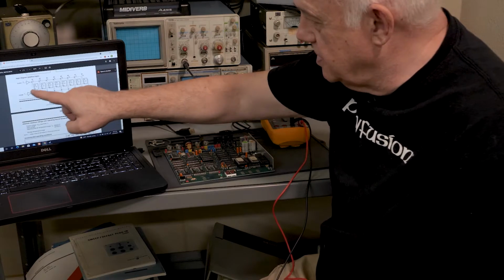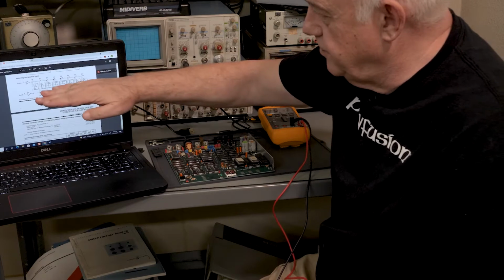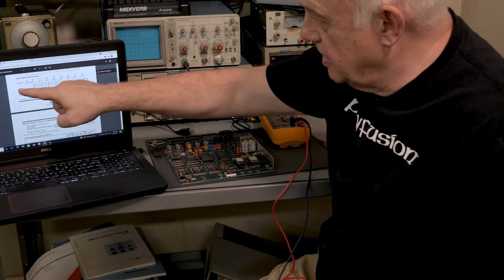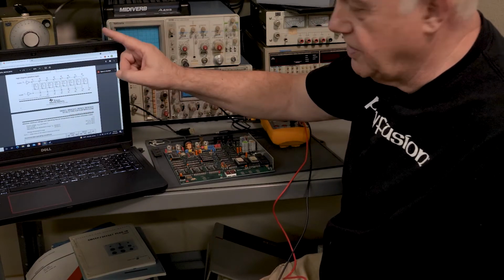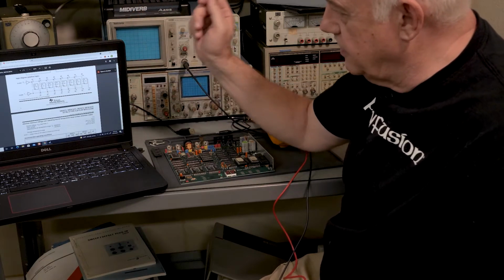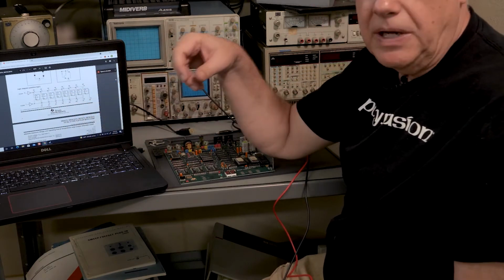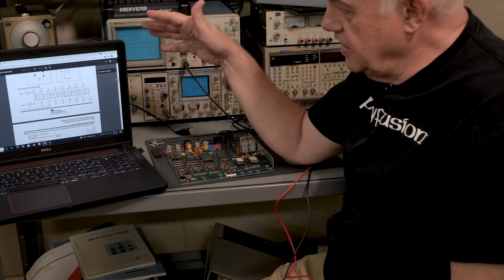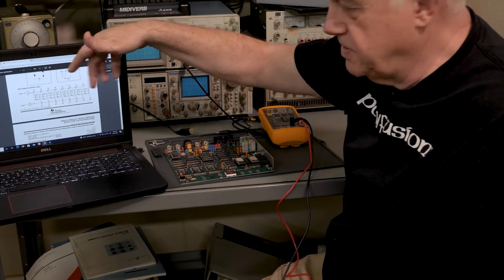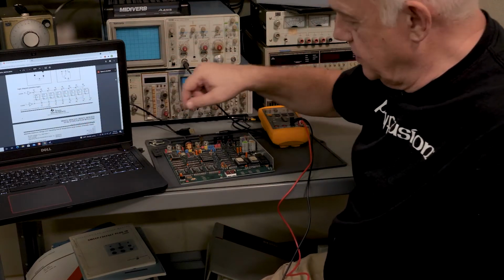You can see it has 8 individual flip-flops, 8 bits of data going in, 8 bits of data going out, a common clear that sets all the flip-flops to 0, and a common clock. This one happens to be rising edge. You can have rising and falling edge. Rising edge will latch everything in there. Notice the flip-flops are labeled 1 through 8. Now, most data bits are labeled 0 through 7, but it's important to know that these are all independent. It doesn't really matter what order you put the stuff in. And then there's a common clock.